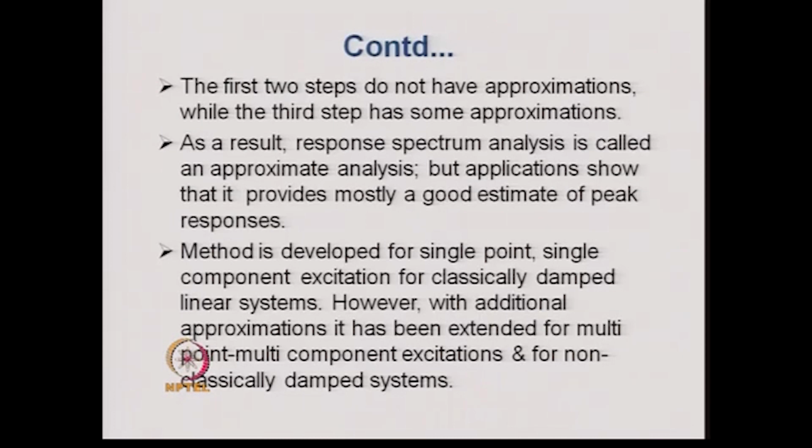The method as such is developed for single point, single component excitation for classically damped linear systems. However, with additional approximations, it has been extended for multi-point, multi-component excitations and for non-classically damped systems.